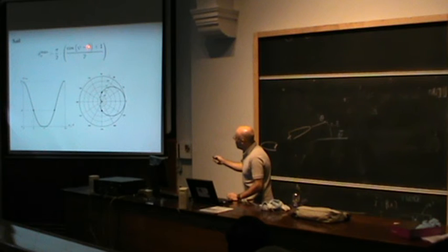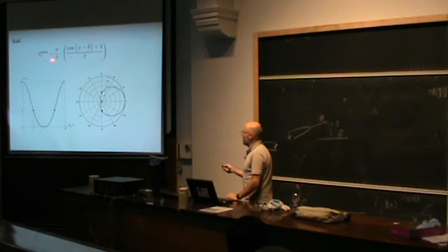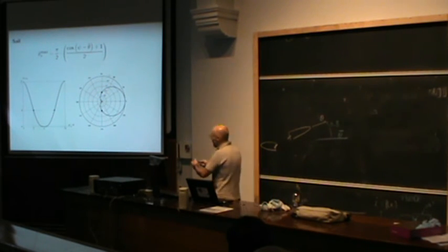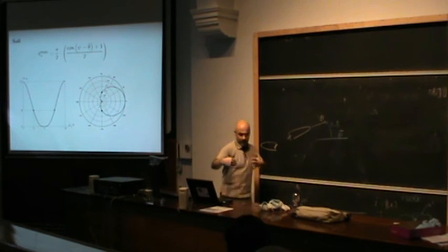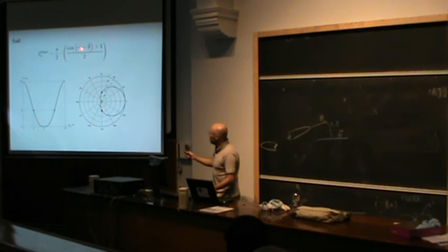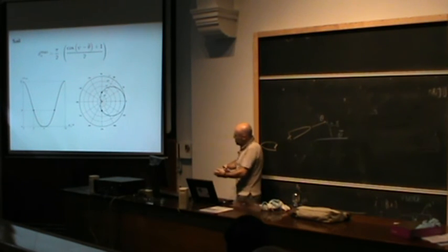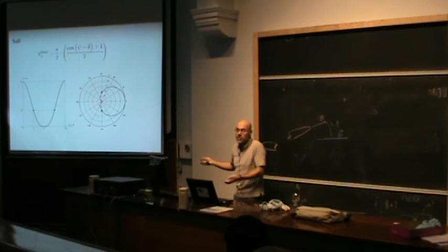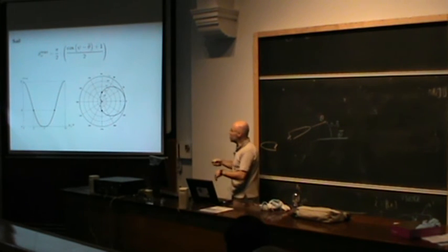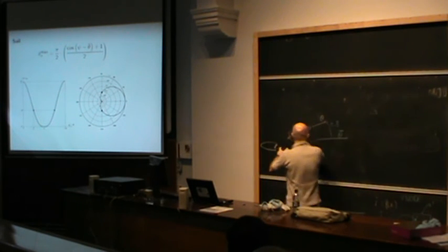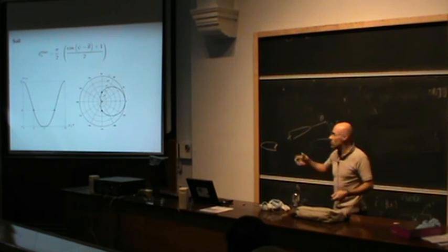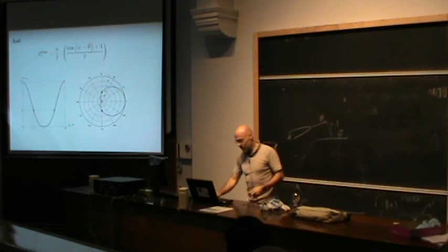Now the same is to be done for the sail, but we look at the difference between the desired heading and the direction of the wind. And then what we call a cardioid model, this, which tells you how to open the sail. It just means that when the wind comes from the back, you open the sail at the maximum. When you are in front of the wind, you close the sail as much as possible. I will not explain, just to tell you that there is no control theory, it's just a pragmatic approach to find a controller for this kind of system.